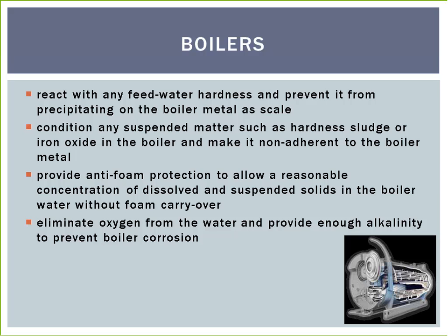The choice of product and the dose required will depend on whether a deaerating heater is used. Also, anti-foaming or anti-priming agents are a mixture of surface active agents that modify the surface tension of a liquid, remove foam, and prevent the carryover of fine water particles in the steam.